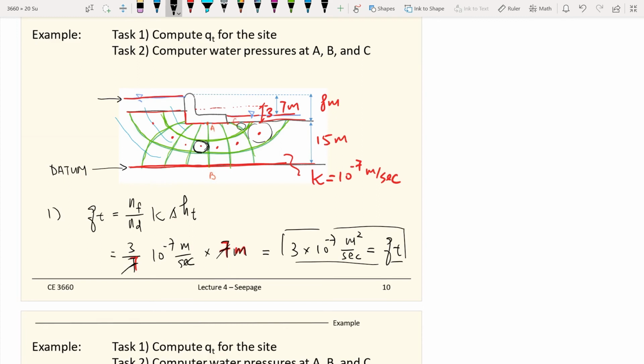So and then also we care about the total head, which equals the elevation head plus the potential head. At the upstream, we define the water table as open to the atmospheric pressure. So the potential head over there is equal to 0, and the elevation head will be 23 meters for this case. So the total head at upstream will be equal to 23 meters.